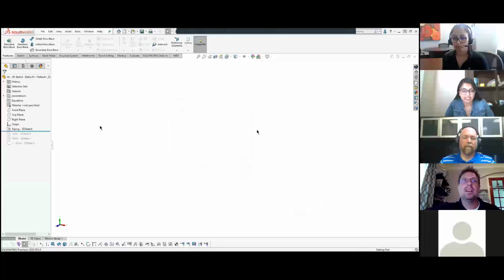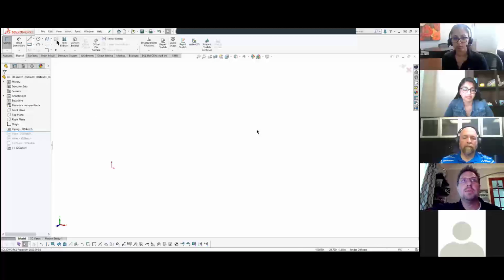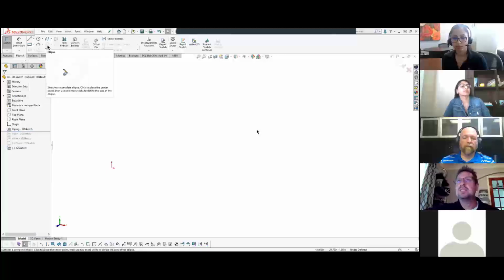So that's select contour. So next I'm going to go into 3D sketching. And 3D sketching is on the little drop down right here. So you're going to insert a new 3D sketch. And when you do that, you'll see some of these things ghost out. So I can't do like slots. Things that have to belong on a 2D plane, you can't really create.